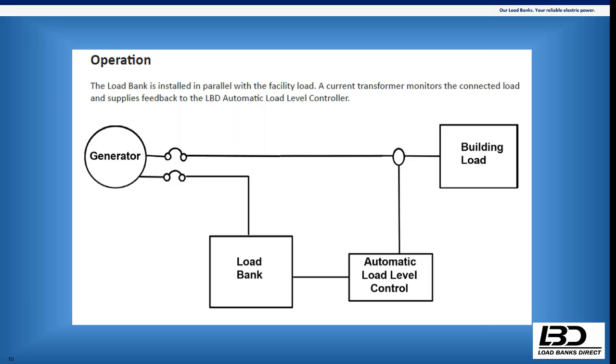Yeah, another thing I would add, Eric, is that the customer also gets a feedback signal. For example, we have a master relay we call K100. It's a safety relay, and it's tied into the air fail circuit, the overtemp safety circuit, and it also gives indication that the blower contactor is energized and the blower is running.